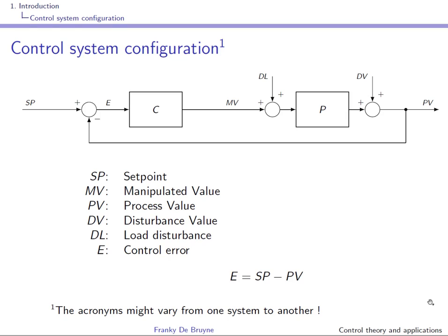In some cases, we will complexify this control system configuration to take into account the disturbance dynamics for systems such as the LTR 700 system or the TC Lab system. So what we'll do is take into account the disturbance dynamics. Here we have written D. Again, I have left out the s dependence for simplicity of notation, but of course behind this D is a transfer function D(s).